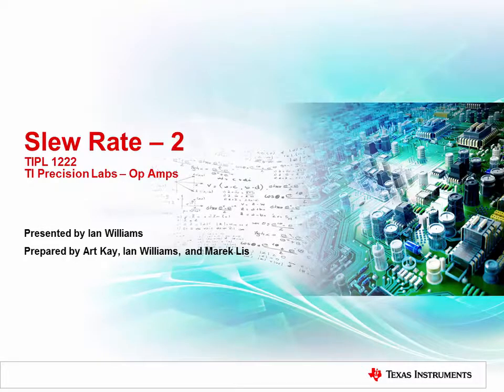Hello, and welcome to the TI Precision Lab discussing op-amp slew rate Part 2. In this video, we'll discuss the body effect's impact on slew rate, take a look at settling time, discuss the differences between an amplifier's small signal and large signal step response, and relate small signal step response to stability.